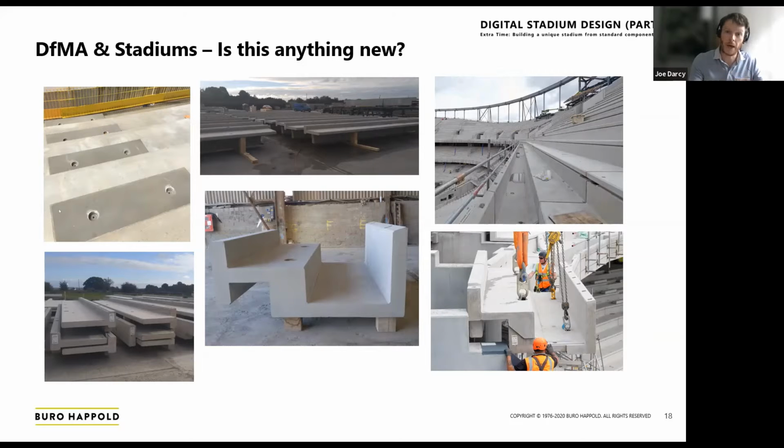We are very much aware of the desired design from a manufacturing and assembly point of view, i.e. we don't make a terrace unit so large it can't be installed because you can't get a big enough crane, or so long that it can't be taken to site because it can't fit on a truck.